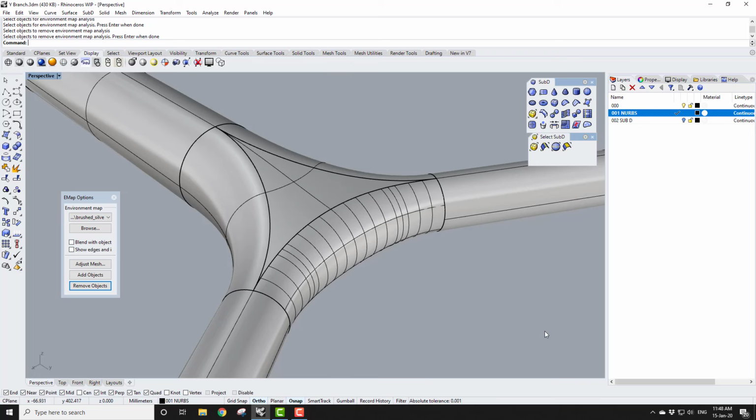There's a number of techniques we can use in NURBS, but the distinct disadvantage of most of them is that if we want to produce iterations or refinements of the shape, then this can be time consuming, as we have to concern ourselves not only with controlling the shape, but also matching the continuity across the different surfaces.